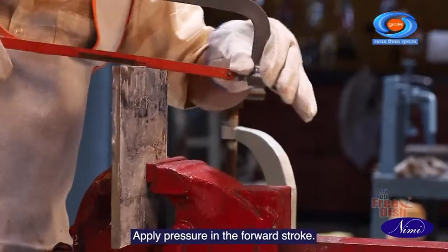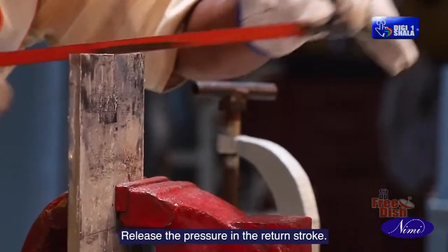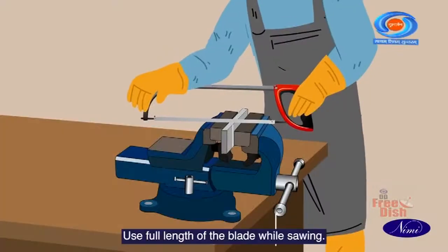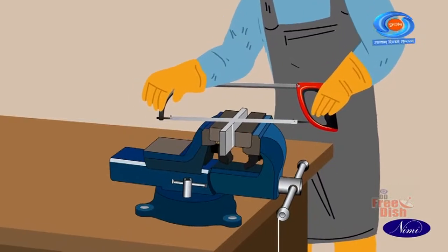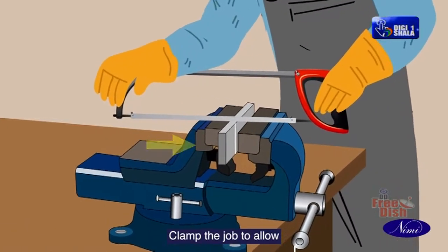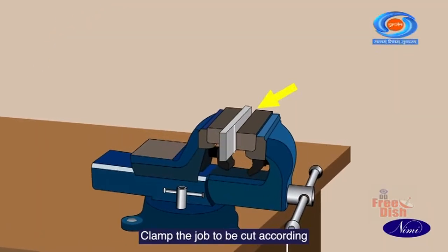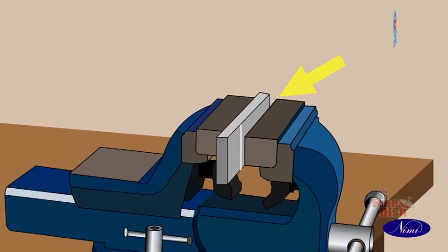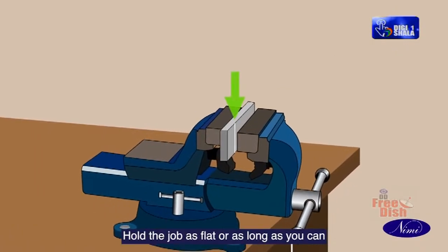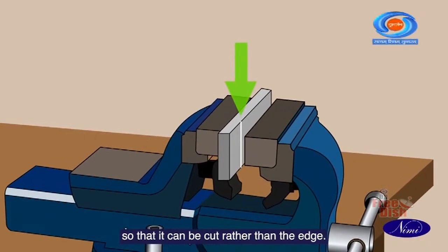Apply pressure in the forward stroke. Release the pressure in the return stroke. Use full length of the blade while sawing. Clamp the job to allow sawing towards the overhanging end. Clamp the job to be cut according to the cross section for sawing. Hold the job as flat or as long as you can so that it can be cut rather than the edge.